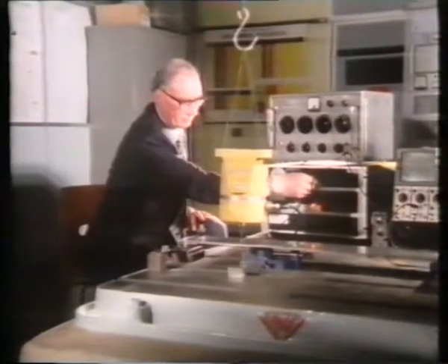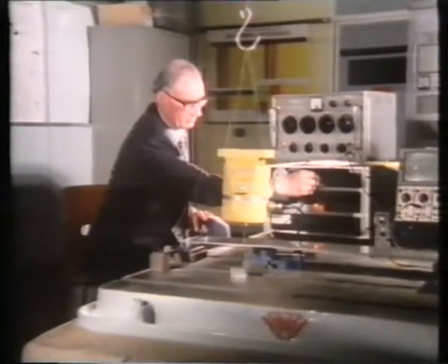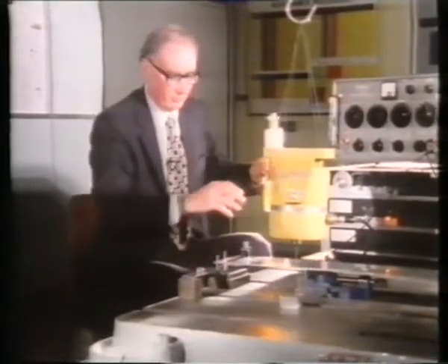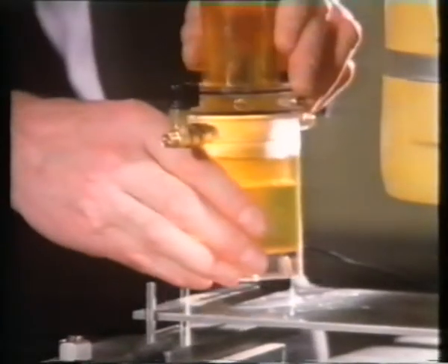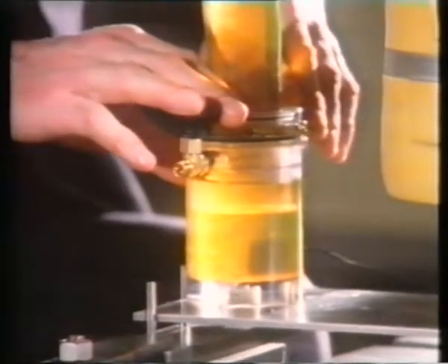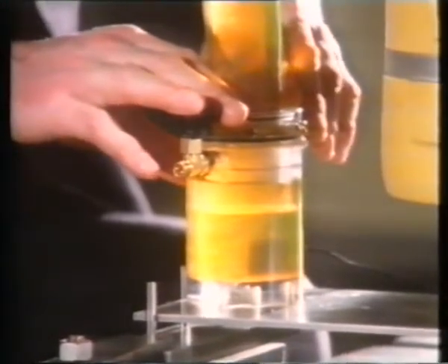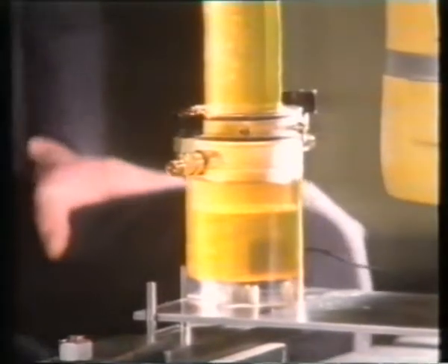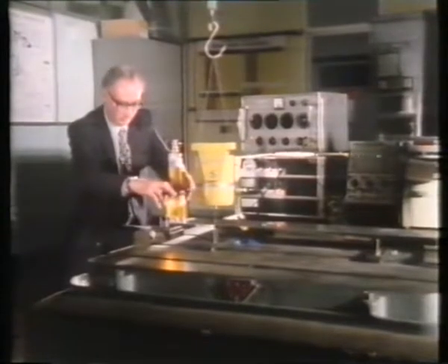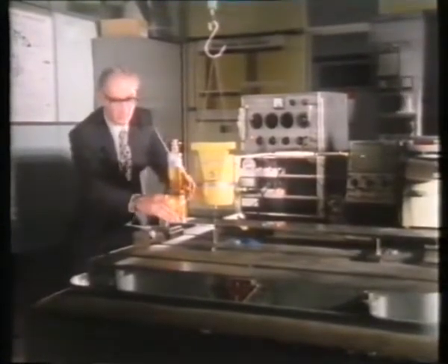I'm now going to absorb the vibration of this single degree system by adding to it another degree, making it a two-degree vibration system, and we'll then tune it in such a way that the energy which you saw being generated by the single degree of freedom system will be absorbed by the second degree of the two-degree system.